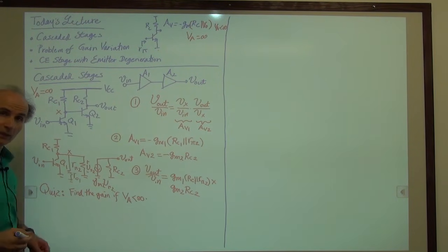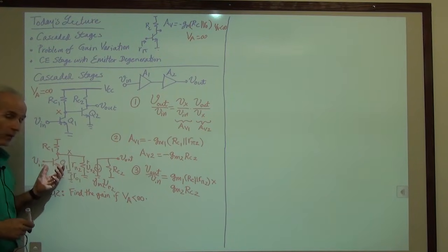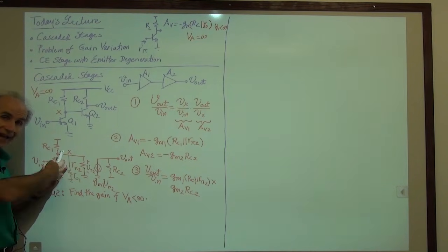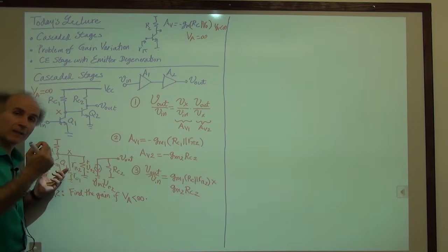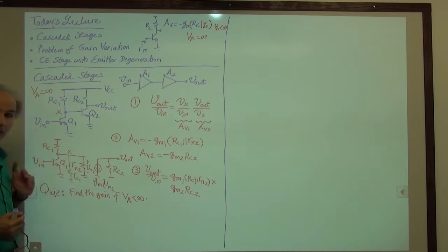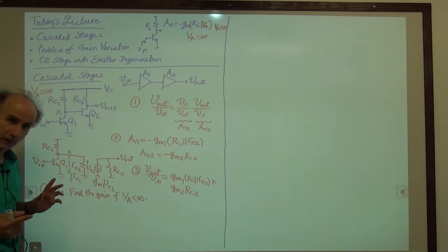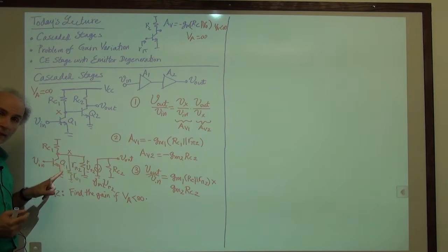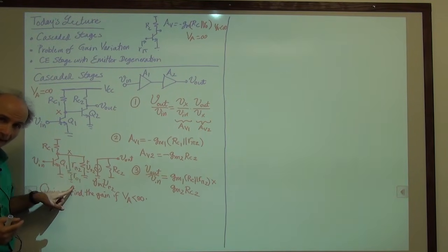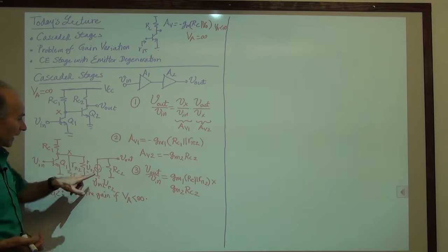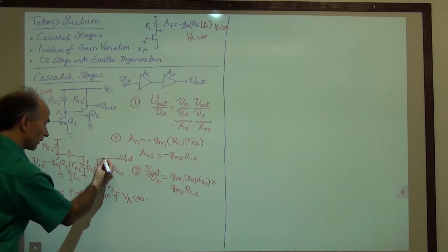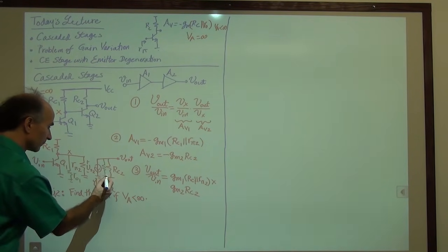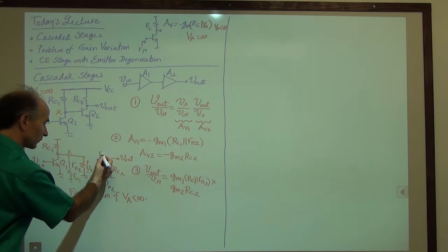And by that, I mean I have a small signal model for Q1. And what I did is I took RO1 out of it and explicitly drew it here. That should not be confusing. So now what's inside Q1 does not have RO1 anymore. We just drew it outside. And for this guy, we draw RO2 here. I'll call it RO2.